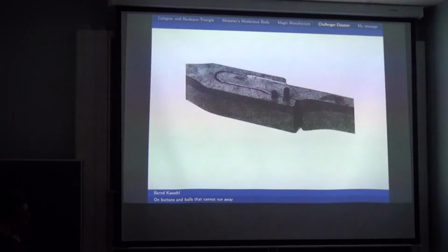But there was another accident that one can find in the official report on this accident, and this is called lack of roundness. So Feynman asked the mechanics, if you reassemble these different parts of the rocket, how do you know that the shape of this pipe is perfectly circular? And they said, well, we have our guidelines, and it says measure the diameter from 6 different directions, and if it is within tolerance, then it is okay. And he said, well, what if it is not within tolerance? Well, then we hammer a little more, and then we measure 12 times to be on the safe side.